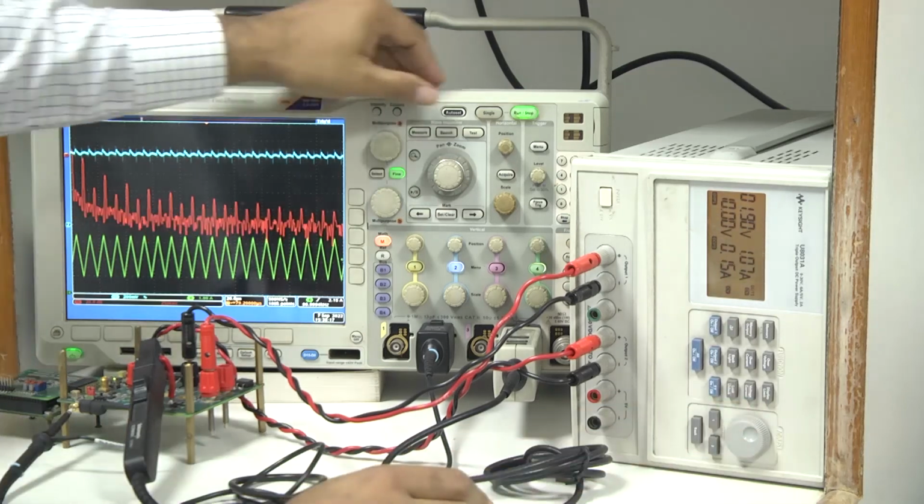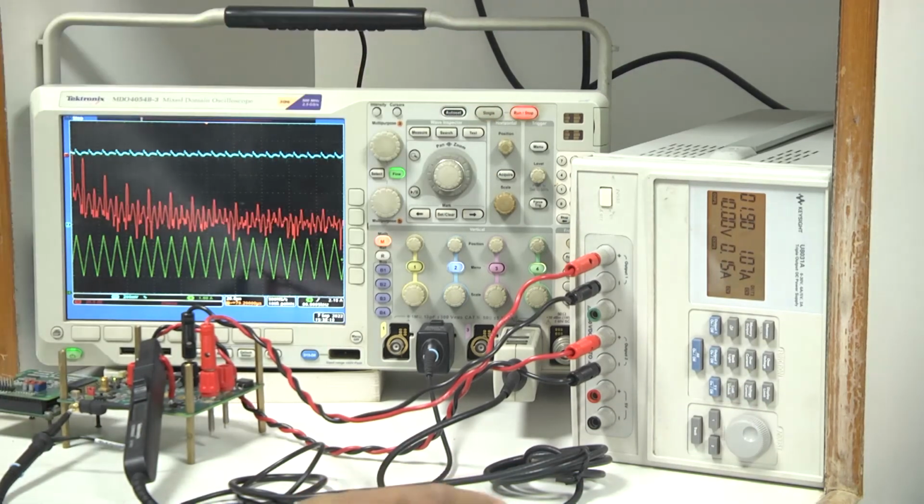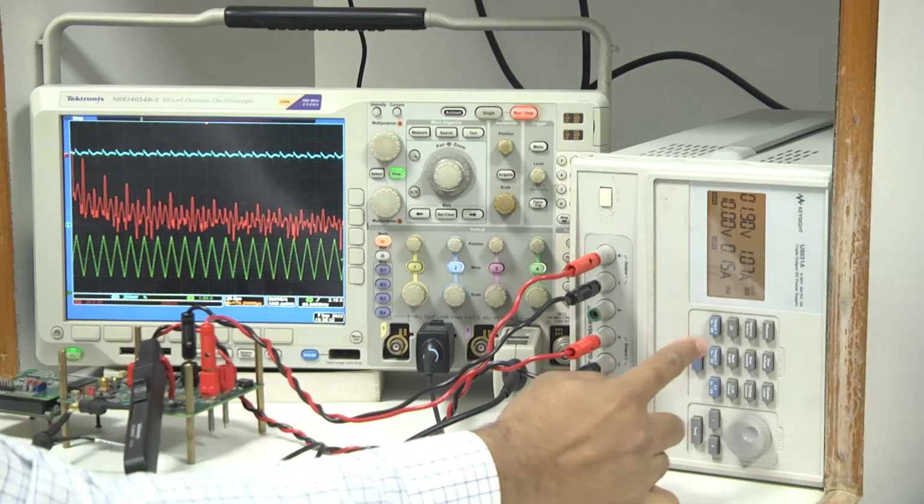it looks like the switching frequency becomes half. There is no component at 200 kilohertz here, so the fundamental is at 100 kilohertz, then all the harmonics. But actually it is set to 200 kilohertz; it is a nonlinear phenomenon that is making it look like 100 kilohertz.